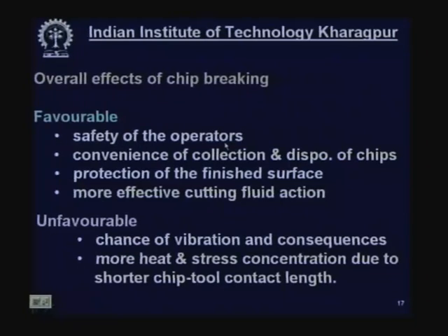to the operator. And I remember while doing my PhD, in my earlier days, one of my colleagues was conducting one experiment on machinability of a ductile material, say steel, at high speed. Chip was coming out. So, for research purposes, he used a flat type, negative rake flat type cutting tool without any chip breaker, and the cutting speed was increased. The chip was coming out very fast, and it was creating problems.